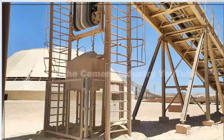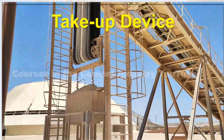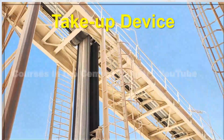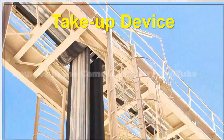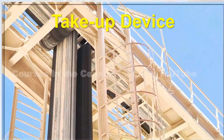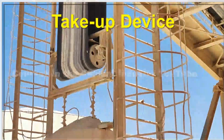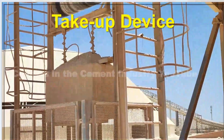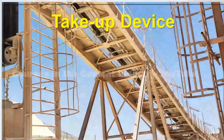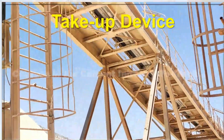In this course we will explain the take-up device. The system incorporates mechanical or automatic tensioning devices, or take-up, to make sure that the belt remains tight against the drive pulleys, to reduce slippage and improve energy efficiency. The automatic tensioning device is often referred to as a gravity take-up or a counterweight. Take-up devices are installed on the conveyor return side, to ensure suitable tension of the belt against the drive pulleys, and the automatic take-up.